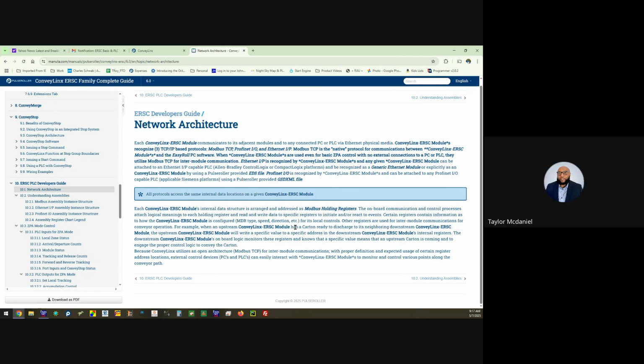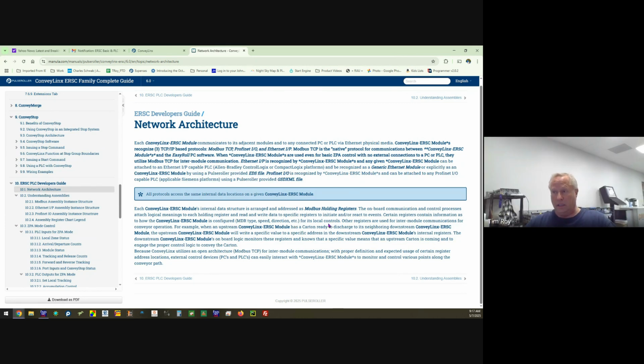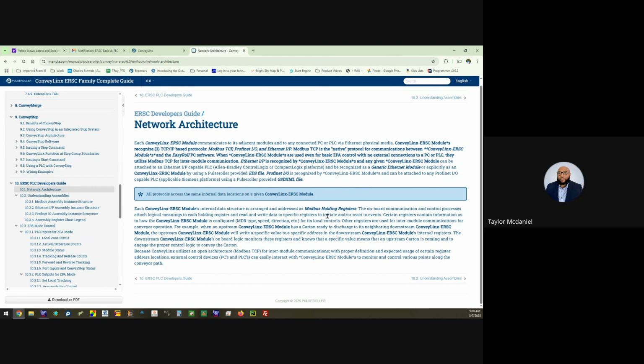Oh, okay. Nice. One item just to be aware of in case it ever comes up: when you use CodeSys, CodeSys expects ODVA firmware. So that would mean your current system could not use a CodeSys type of processor unless we upgrade all the modules and make sure we use all the current files with the CodeSys system. Gotcha.